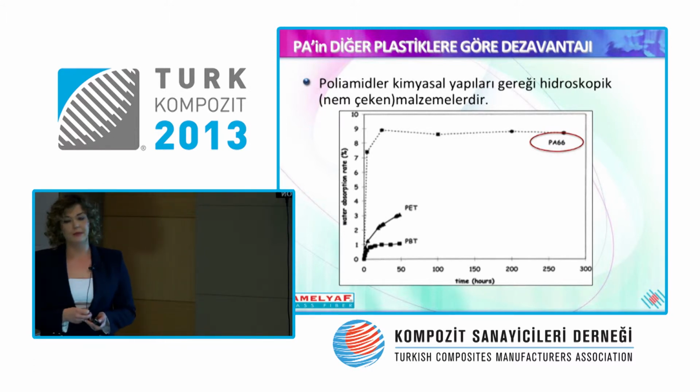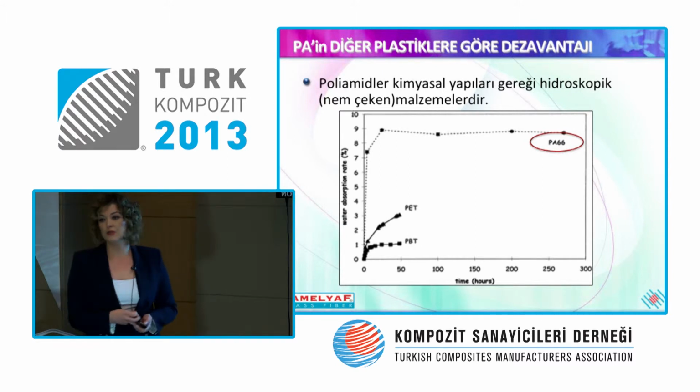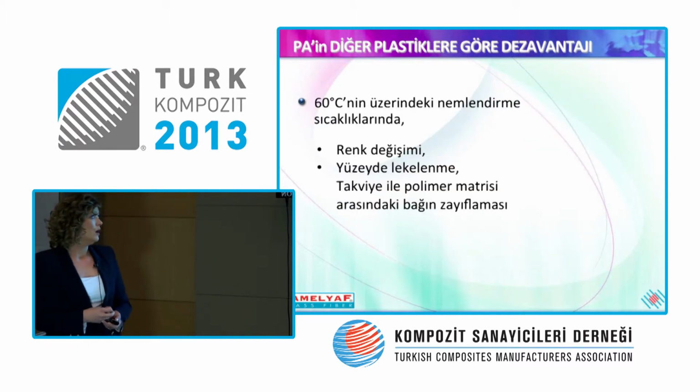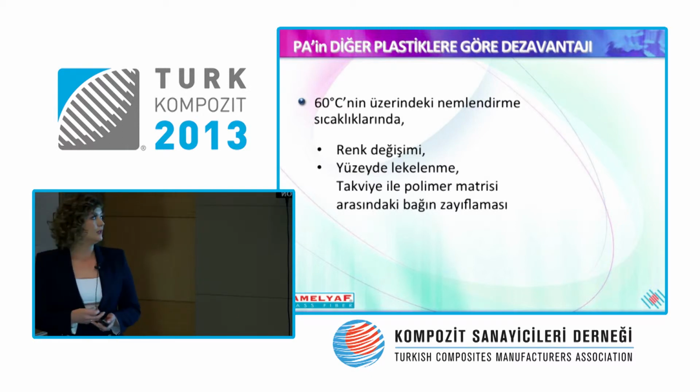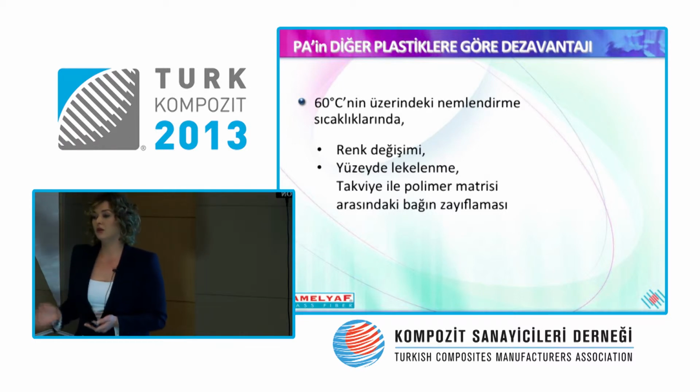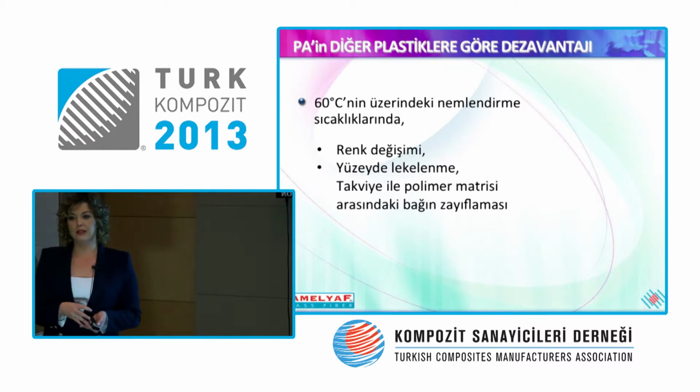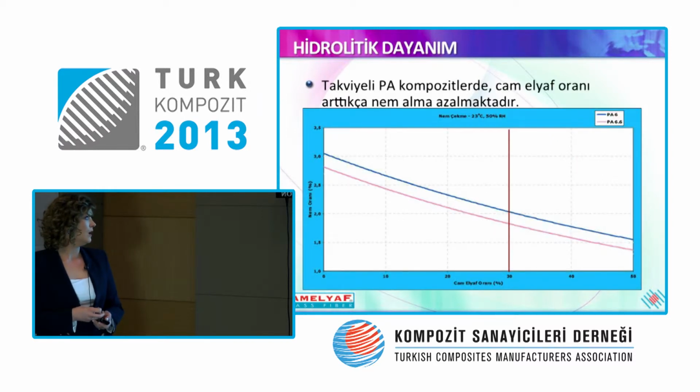Polyamides, due to their chemical structure, are hygroscopic, so they are moisture absorbing materials. As you can see on the table, when compared to PET and PBT, nylon 66 has the highest degree of moisture absorption. This is a disadvantage, especially when the moisture temperatures are above 60 degrees. There will be a change on the color, staining on the surface. There will be a bonding weakening in between the polymer matrix and the reinforcement. So these are all the disadvantages.